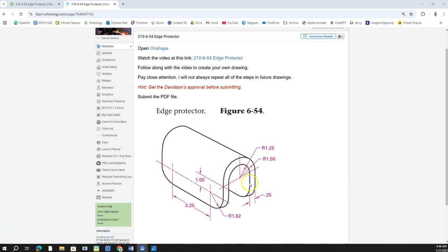So we're going to probably draw this view, extrude it back the length that we have, which is 1.62 plus 3.5 plus 1.62 gets us to the end. And we'll let the computer do the math for us at that point, and then we'll go from there. All right, so we'll look at those radii. Look at that. Look at the thickness there. Make sure you got that down.